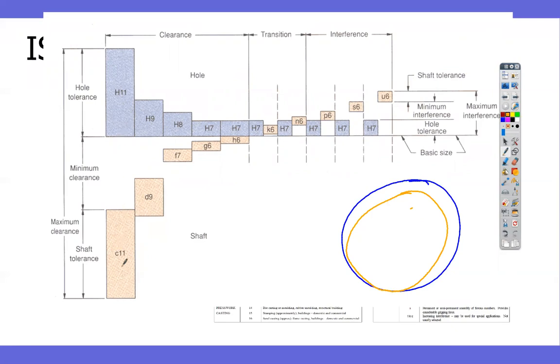The shaded area is how big the tolerance zone is, so what the sizes are. They're both touching the same side. Measuring from here to here, and here, that's the difference in diameter that I can have for that shaft. Does that make sense? Kind of.